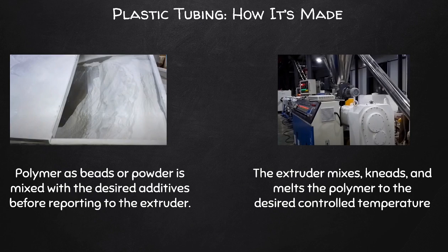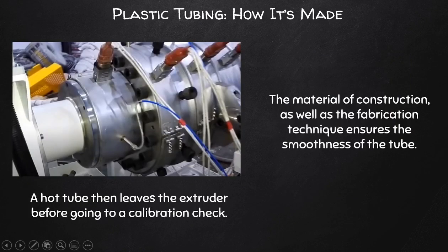And then eventually this melt is pressed through a die. What exits is a fully formed tube. This tube is then checked for any defects. Usually you use something like a laser. You check the tolerances, the wall thickness. Right. This pipe is typically produced with an inherently low surface roughness compared to a steel pipe. All right, so